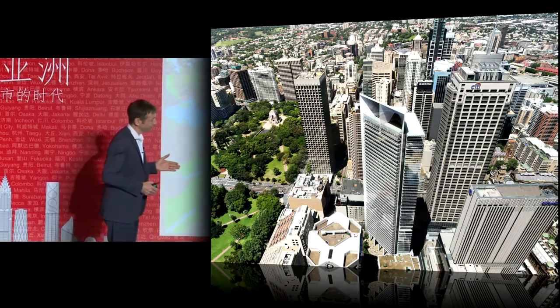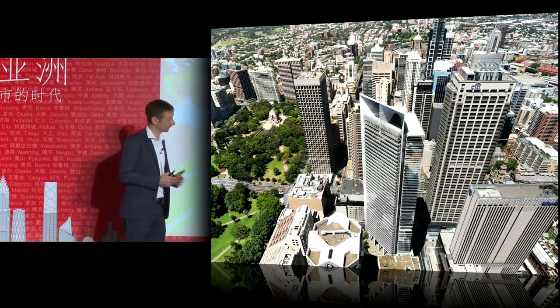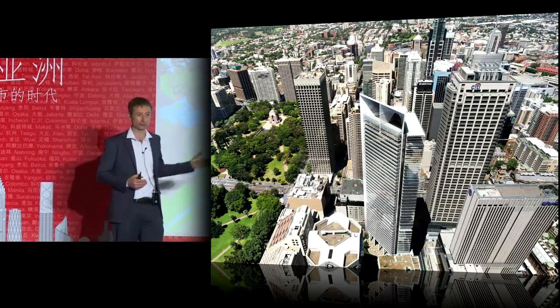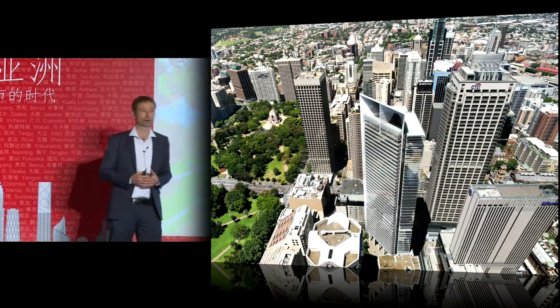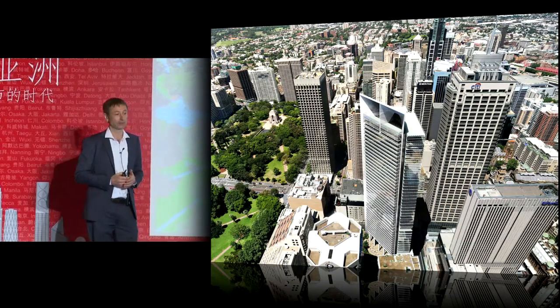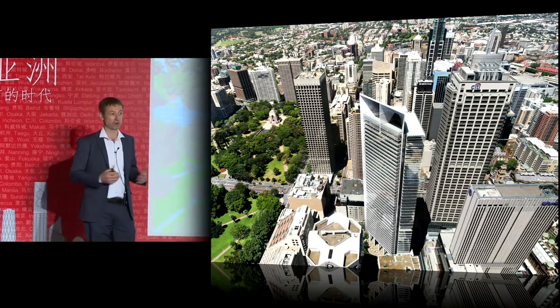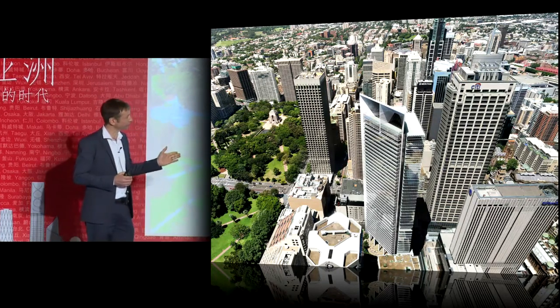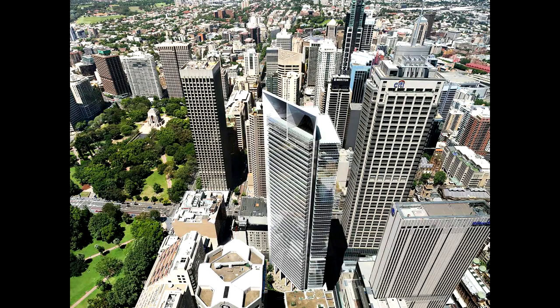Typically, it's a chilled water system. If you start with the facade, it's got a very high performance facade. We've got a visual light transmission on the northeast here of around about 55% with a shading coefficient of about 0.26 on the west, east and north facade, and the north facade is actually quite a small facade down through here. The shading coefficient is down to about 0.23. So it's a very, very high performing facade building.